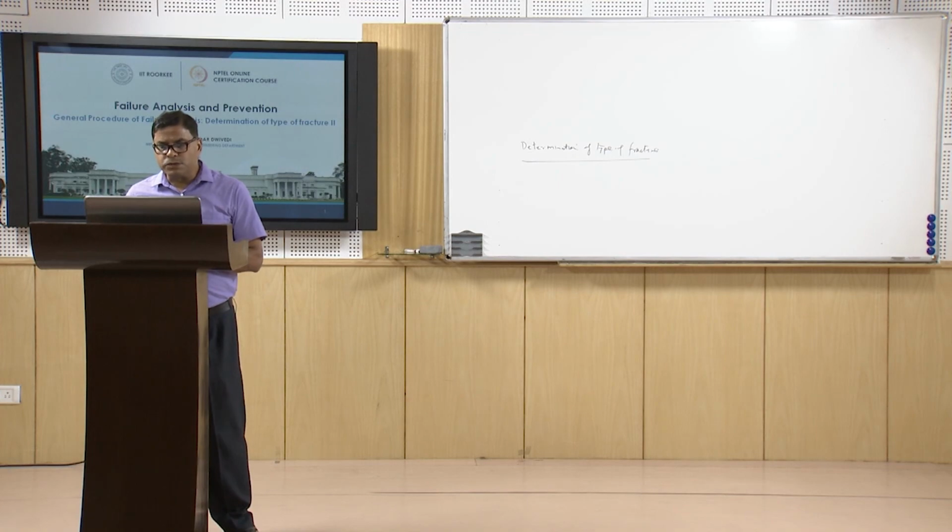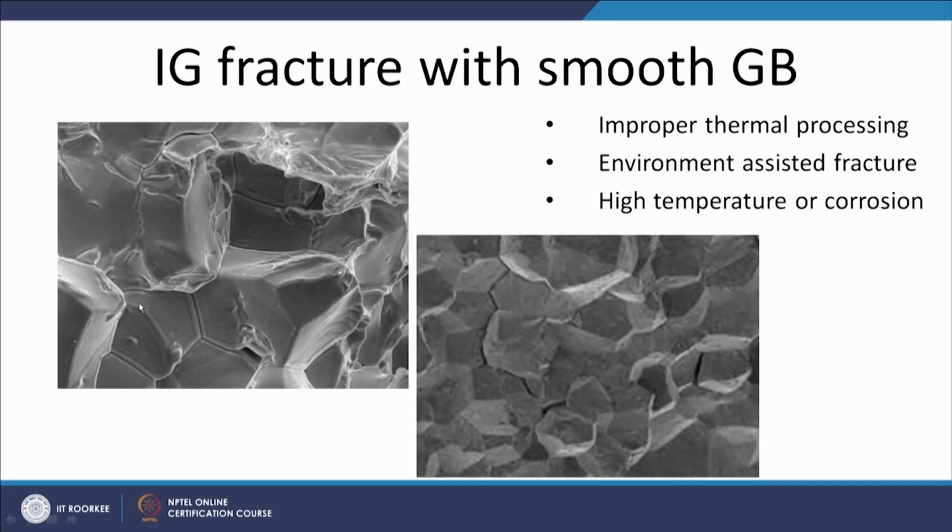So, in this case, what we can see is that the grains are very smooth and have a ball shape. We can see these are like footballs, different footballs segregated together. Sometimes secondary cracks can also be seen at the grain boundary area. The primary crack is the one responsible for separation of the surfaces through all the grains, but there are some additional secondary cracks also present between the grains.